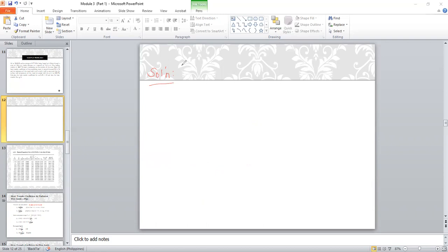The first thing that you're going to do, actually, if you're not going to follow the way it's given in the book on how the particular problem is to be solved, you're going to start with the formula that will lead you to the required information. So the required information is the h, the heat transfer coefficient, and we need as well to get the ratio of the Q to A, or that's the heat flux. Now, before we can even determine the heat transfer rate, there's a need for us to establish the flow.